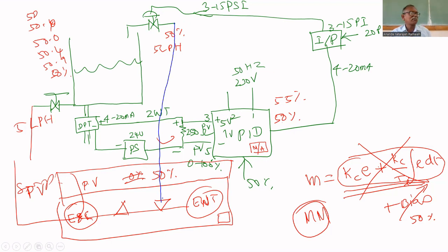That is called disturbance. Any disturbance comes because of voltage changes, flow rate will change. But the controller takes action. Immediately it will open more. For low voltage, it will give the same flow rate. So that level again comes to 50. Have you understood this point? That is called control. Even if you come after 1 week, it will remain at 50%. That is called closed loop control.